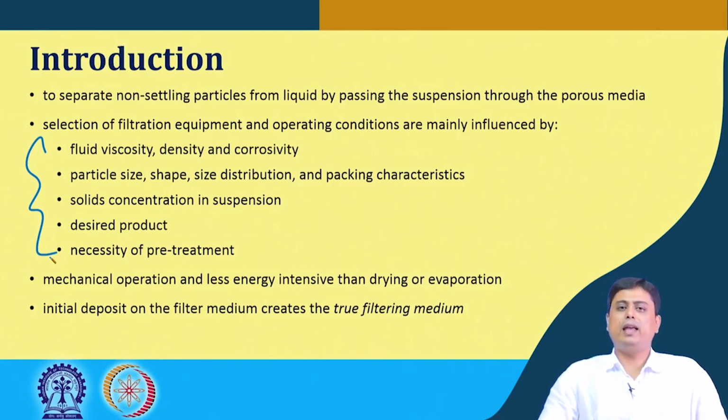The flow is effectively happening through that cake, in cake filtration particularly, and what cake filtration is we will come to that. But mainly these solid particles either stick to the filter media, or go inside the filter media and attach there, so that the tortuous paths get clogged. Quite naturally, that means the particle size, shape, distribution and packing characteristics are important in such phenomena.